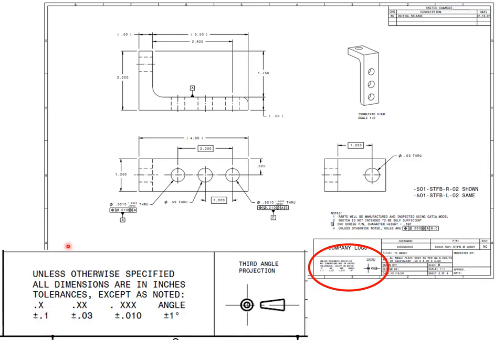Okay, so another thing we see in a title block is what projection are you using? Again, in this class, we're only going to stick to third angle projection. If you were looking at a first angle projection, this cone shape would be over on the left side. Again, in this class, we're only going to stick to third angle projection, and this is the symbol for third angle. And again, this is your typical title block and border.